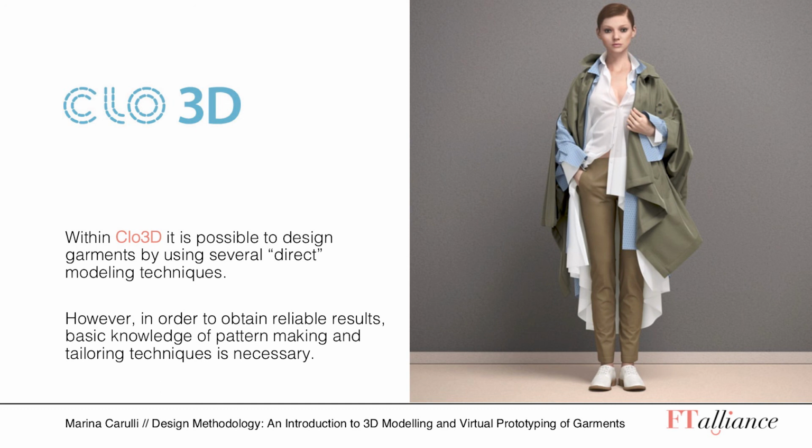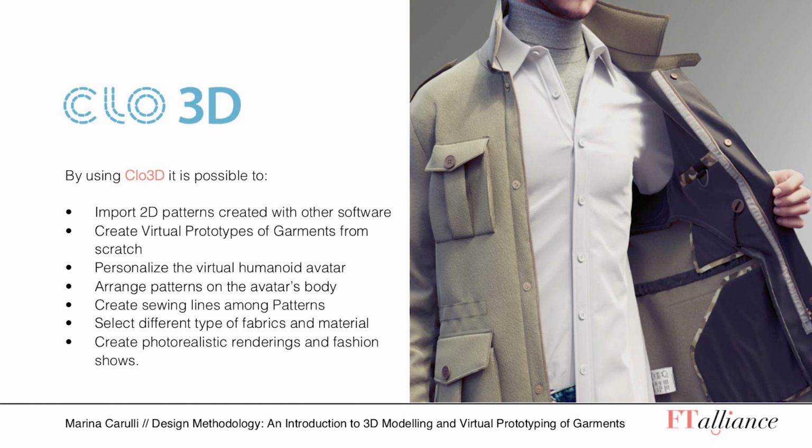However, as for the other just presented softwares, in order to obtain reliable results, basic knowledge of pattern making and tailoring techniques is necessary. In Clo 3D, we have a huge range of possibilities for creating and personalizing the virtual prototypes of garments. More specifically, by using Clo 3D, it is possible to import bidimensional patterns created with other software, but also to create virtual prototypes of garments starting from scratch in Clo 3D. Also, it is possible to personalize the virtual humanoid avatar, so our virtual dummies, and arrange patterns on the avatar's body. Then, in Clo 3D, it is also possible to create sewing lines among patterns and select different types of fabrics and materials. Finally, we can also create photorealistic renderings and fashion shows.